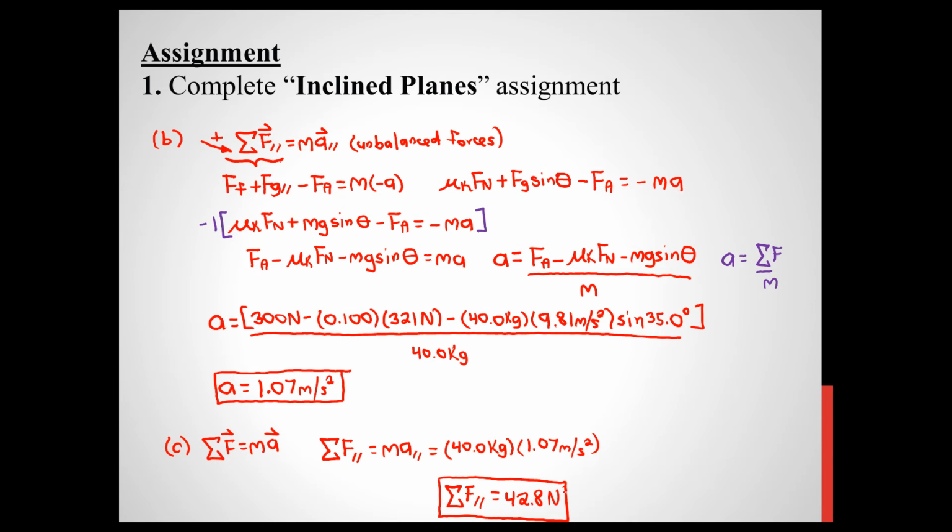And that's it. So when dealing with an inclined plane, as long as you rotate the axis, it'll make our calculations much, much easier. And that is the exact problem-solving strategy we want to use. Otherwise, it's just business as usual, where we mathematically model the situation by drawing free body mass acceleration diagrams and then writing and expanding equations of motion. So in the meantime, you need to complete the assignment called Inclined Planes, and I'll talk to you next time in the final lecture for dynamics on Newton's third law of motion.